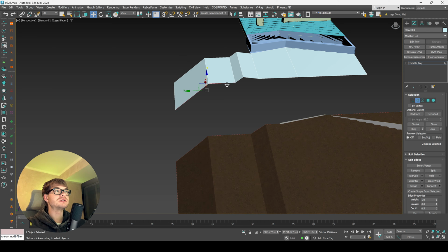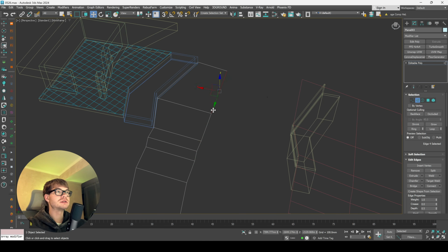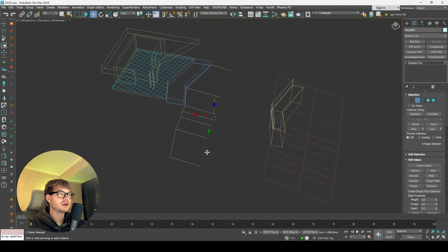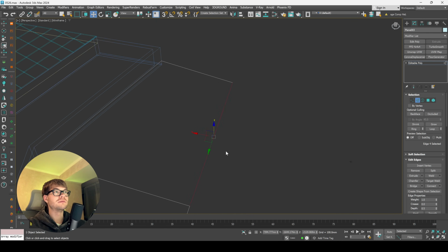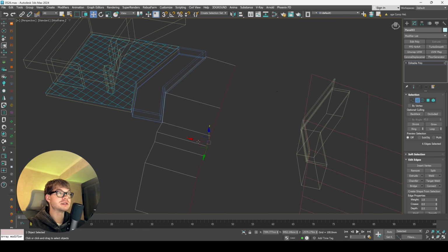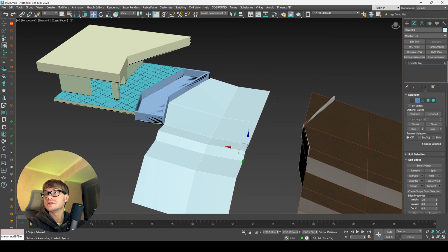Something like this. And now let's select our hollow spline. And here's a little life hack. If you want to select all these lines from this shape, you can simply select one shape right here and double click to select it faster and move it this way.